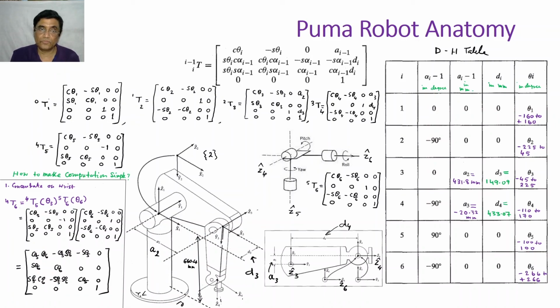That means wherever you see motion, assign Z axis. And then between two Z axis, common normal, you assign X axis. Like that. Between two successive X axis, you assign D. Okay. All kind of thing you know. But specifically to this particular PUMA robot, how generalized DH principle will be implemented, I just told you. And after that, I will develop further model.